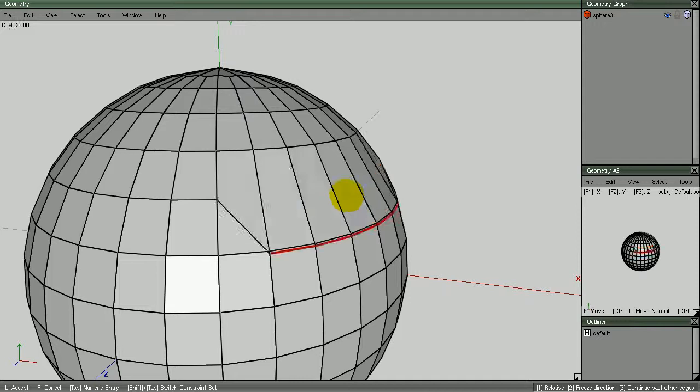So, let's see, by holding my control, I think I have my control set to 0.1 for distance constraints. So that's how I can do that there. I think my alt is at 0.01, yeah. So that is the absolute movement. Now if we toggle our 1 key, or hit our 1 key, and go to relative movement, you see the upper left hand corner changes to percentages.